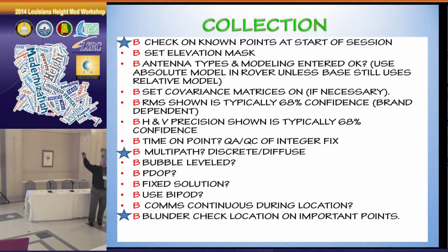The elevation mask, I recommend 10 for real time. That's what I use. It eliminates the noisiest data, but it still allows most of the data in.